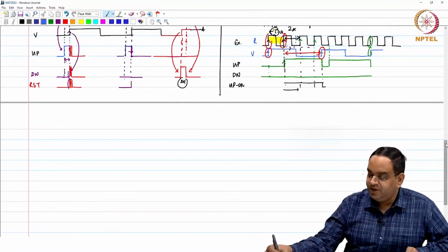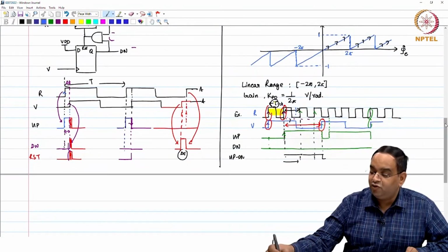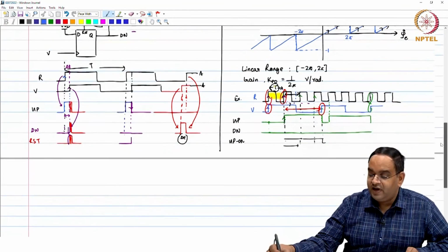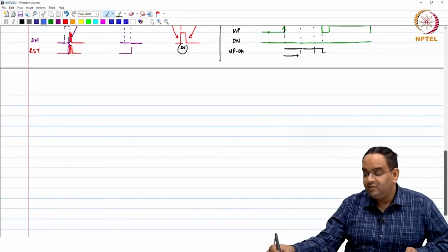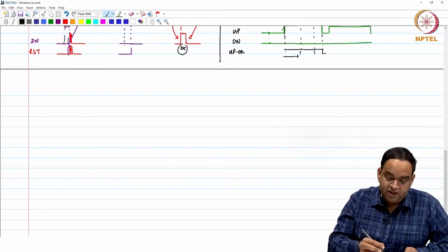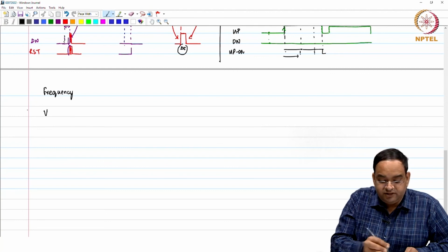Now, you may ask me about the transfer function as a frequency detector. So, what I have shown you is the average of the PFD output. Now, if I just want to use it as a frequency detector, well, you can use it simply as a frequency detector, and then it has frequency transfer characteristics. Well, it comes after a good amount of maths, so I will skip the maths here. I will just show you what kind of frequency transfer characteristics the PFD has.